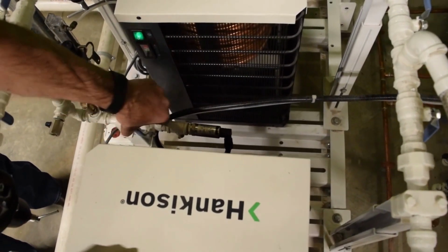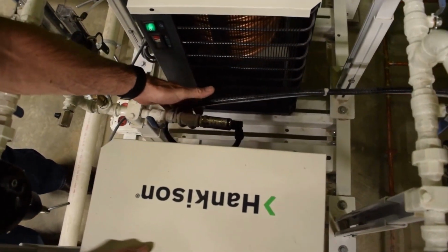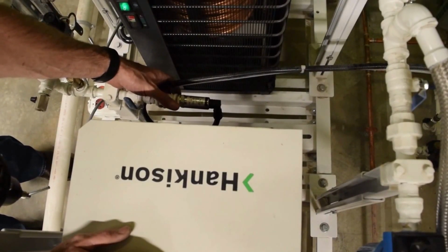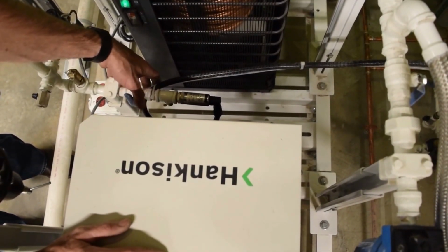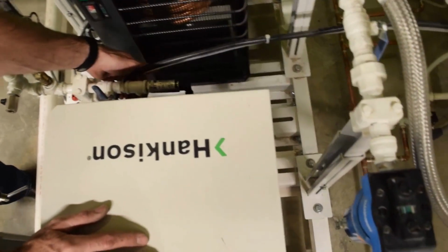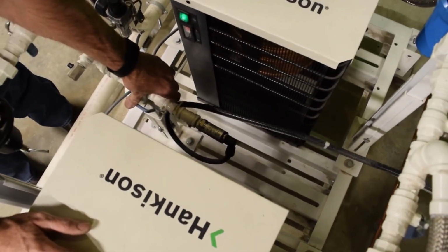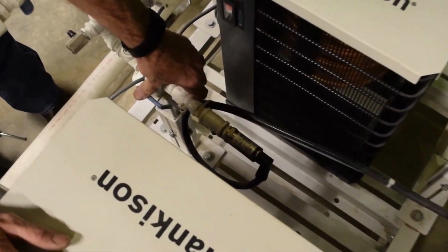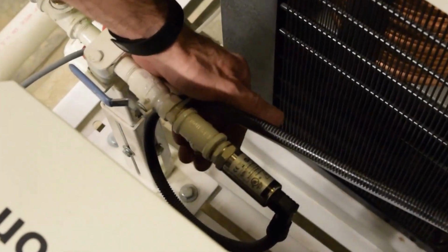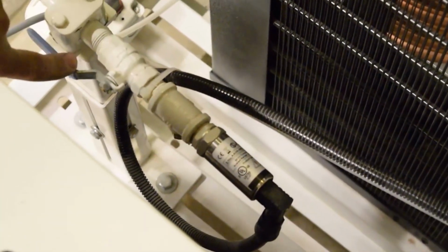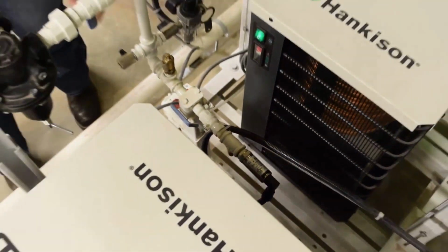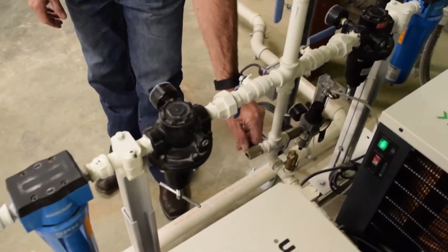If you valve this off like that, the hissing stops, but then your dew point's going to go up, and it's not a real dew point. You're going to get a high dew point alarm. So if somebody tightens that so the hissing stops, or valves that off, you could get a high dew point. You will get a high dew point and not know why. So you always want to make sure you hear a slight hissing sound right there, and you want to make sure that valve's on.